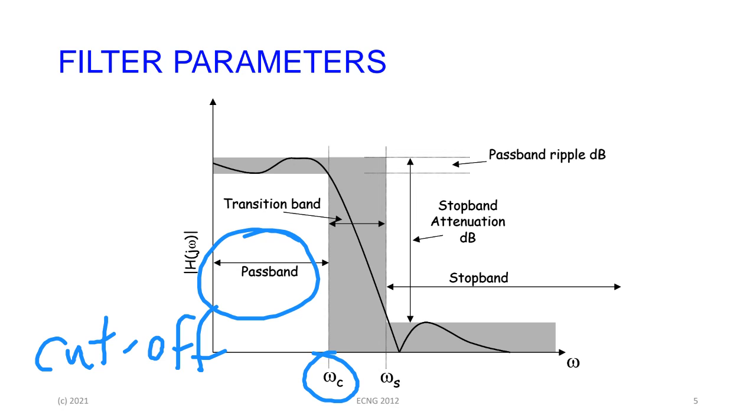So an ideal filter is supposed to pass everything in the pass band, and then as it reaches the cutoff, it stops. And then everything in the next band, which is what we call the stop band, is supposed to be stopped, absolutely stopped. So the red line is how an ideal filter is supposed to work. Well, we know nothing operates like that in the real world.